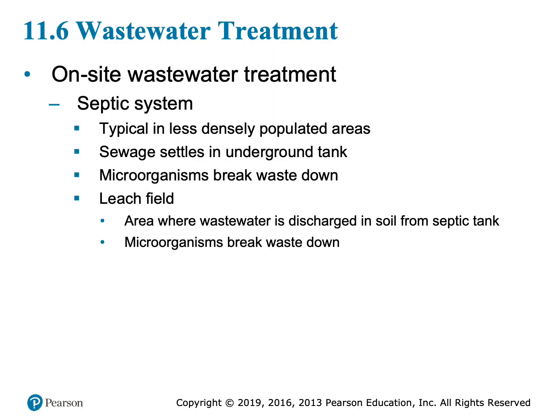On-site wastewater treatment, an example of this is a septic system, and that's your blank under number 1. Households rely on septic systems to treat their water and sewage. It's typically found in less densely populated areas. The sewage settles in an underground tank, and microorganisms break it down. And then the leach field is the area where the wastewater is discharged into the soil and microorganisms continue to break down the wastewater. So leach field is your last blank under your notes.